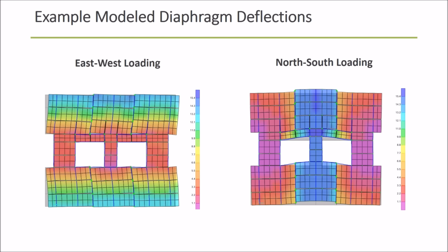So that's well above our design minimum loads from ASCE 7-10, but this was done this way because they wanted to create a diaphragm which remained essentially elastic under the earthquake and will see little damage. That's the intent of this design, but it was a good exercise in how to go through the diaphragm modeling and learn how to do this more complicated diaphragm modeling.